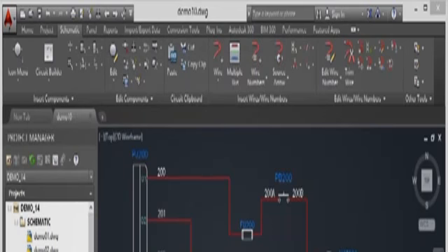It will prompt me if I want to replace my DWG. I'll OK that, that's fine, because what I did previously to this video was tested the locations where the file was going to go. So there was already a file of the same name in there. Now I need a base point so that when I insert my circuit from the icon menu, it knows where to insert it from. I'm going to go for that corner there, the endpoint snap.